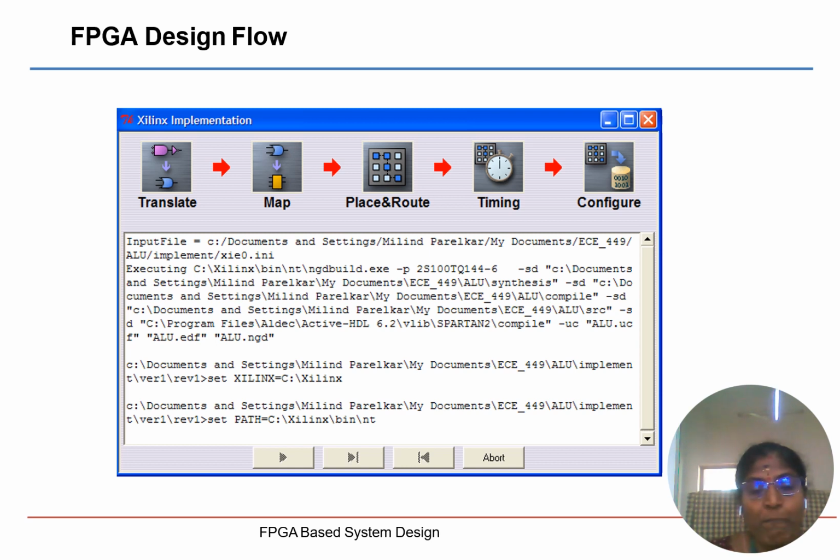Then mapping is nothing but technological mapping. So what is technological mapping? It is going to convert the ordinary gates into NAND and NOR implementation, and the concept is optimization. The next one is decomposition. For example, in the configurable logic block only two inputs are present, or three inputs, which differ depending upon the logic families. We are going to map the translated logic expression into whatever we require.